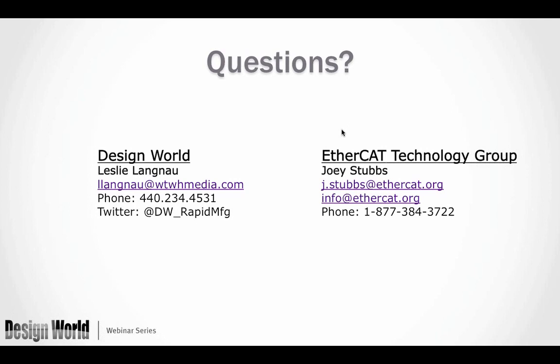With EtherCAT, most slave developers are measuring the actual pins that are being used in the network. So as a developer, you have access to the interrupt pins, and you can put them on a large network and put them on an oscilloscope and measure your jitter. As a device purchaser, so as a device user, you can do a similar thing with, for instance, digital output modules.